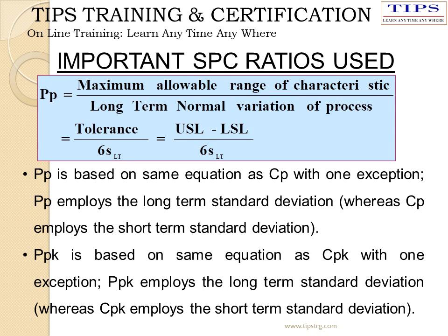Similarly, for the long-term case, PP is calculated. The formula is the same. PP is based on the same equation as CP with one exception, that is PP employs the long-term standard deviation. PPK is based on the same equation as CPK with one exception. PPK employs a long-term standard deviation.